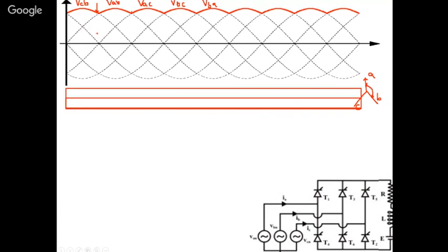So when two phases cross each other, in case of phase voltage, it will be 30 degrees. In case of line voltage, at 60 degrees. Here, two voltages are crossing. Here you can see at 60 degrees, two voltages are crossing. So that will be the initial point, that is a 0 point of firing a thyristor. Because we don't know, we are turning on the supply. How will we know when to start? We are starting at some other instant, the supply will be at some other. So you have to use zero crossing detector and find out when two voltages are crossing. So in case of line voltage, it is at 60 degrees, that is meant to be zero firing.